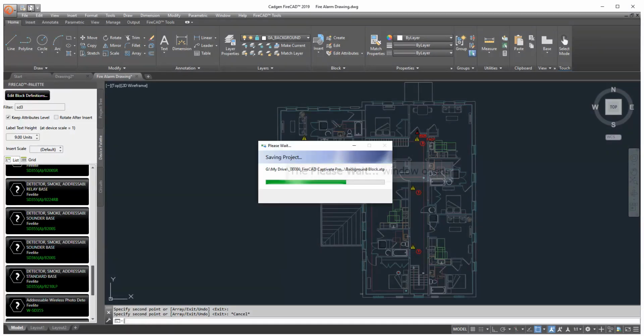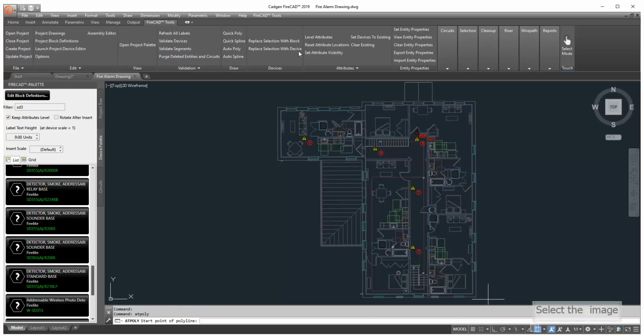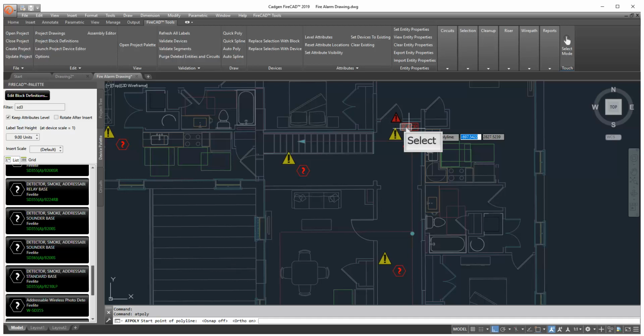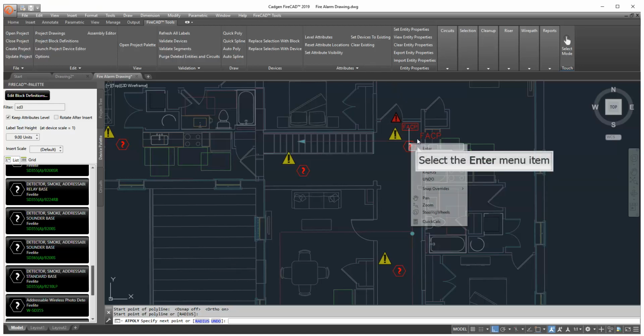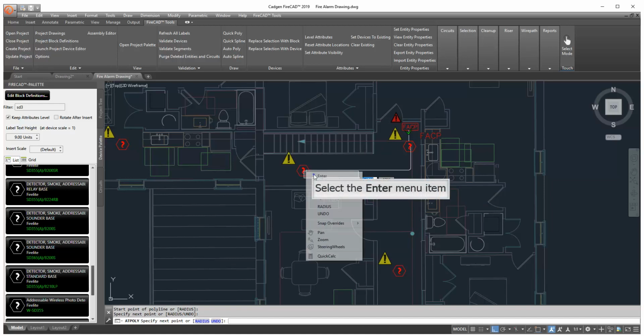That is, when we draw our wire paths, in order to get nice straight wire paths, we're going to turn on the ortho mode and then click using the auto poly command to draw our lines between the devices and get them placed precisely where we want them with nice orthogonal lines trimmed at the edge of the devices.